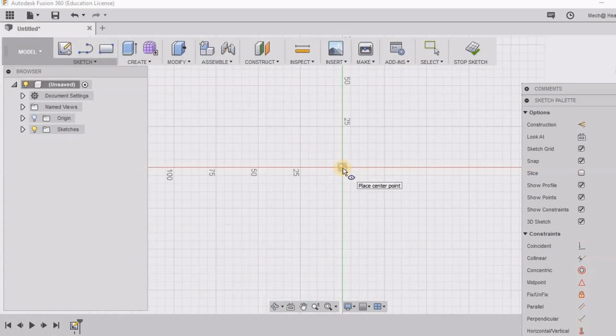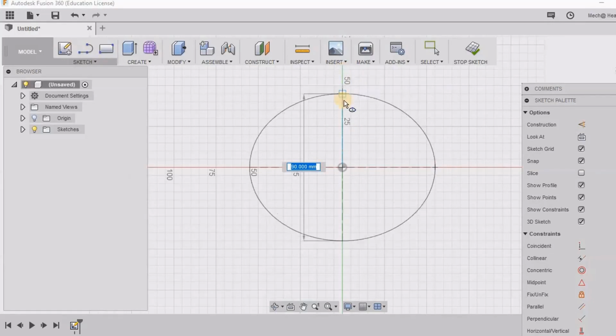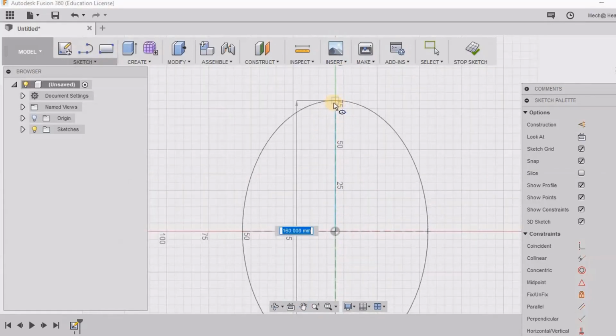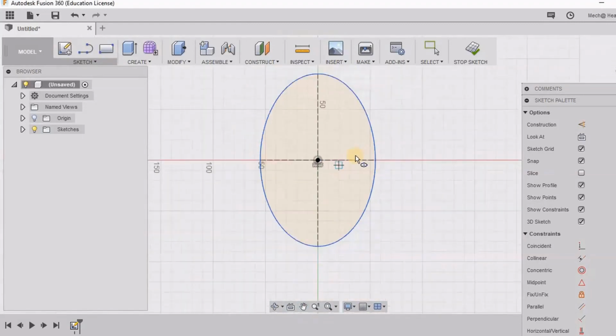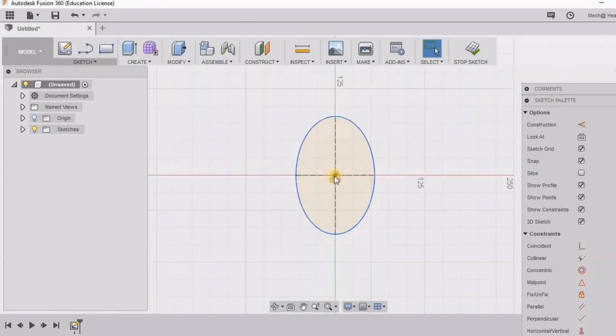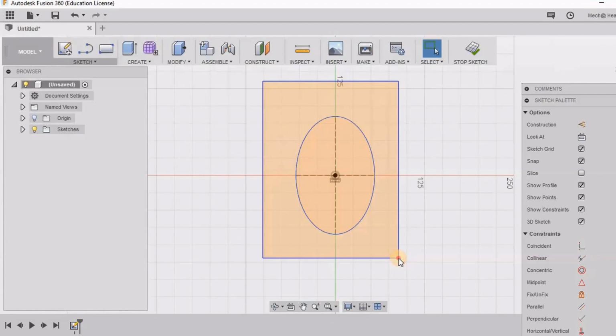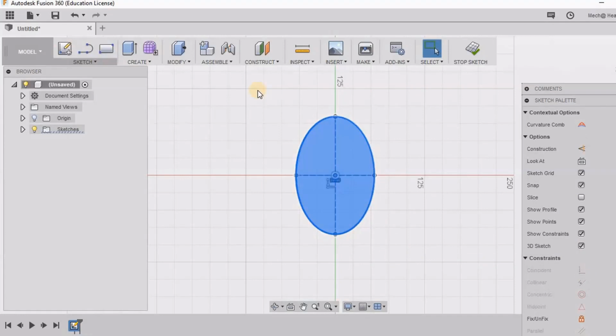So next, the ellipse tool. We have to select the center, then one radius and then the other radius. So this is a very simple tool, just like how you draw the circle. For a circle you will first draw the center point and then the radius or diameter. But here, because we need 2 radii, the major axis radius and the minor axis radius also, we are going to click for 3 points.